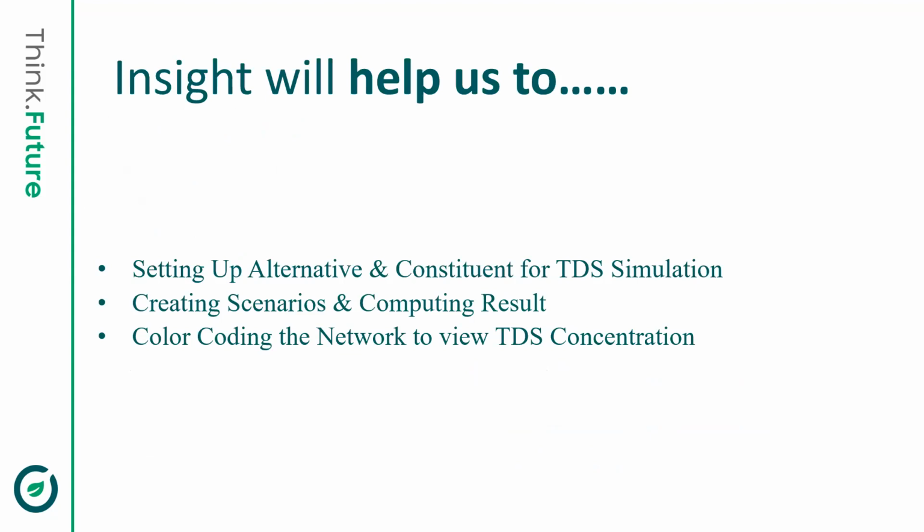The objective of this insight is to analyze water quality monitoring for our distribution network. There are different methods present in WaterGEMS for water quality analysis, like chlorine simulation and water age analysis. But in today's insight, we are going to cover a TDS simulation for a distribution network, which allows a water utility to monitor and analyze the concentration of dissolved solids in their distribution system. This information is crucial for ensuring compliance with regulatory standards and maintaining high water quality.